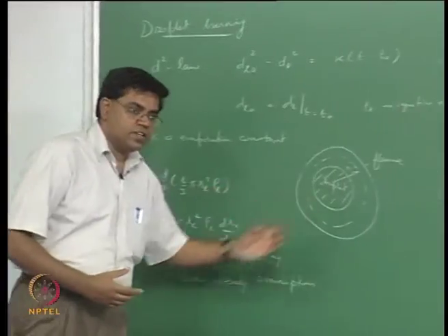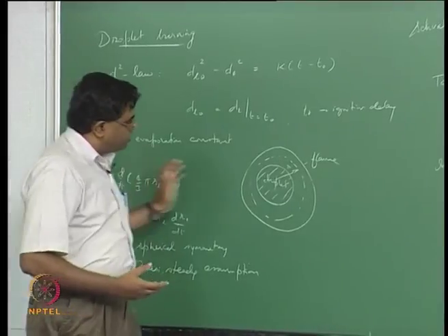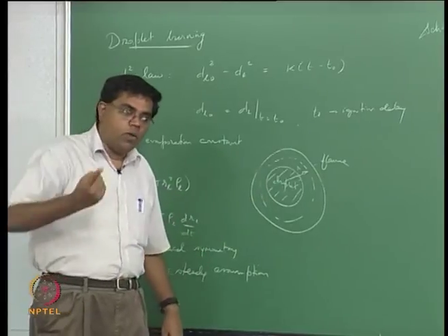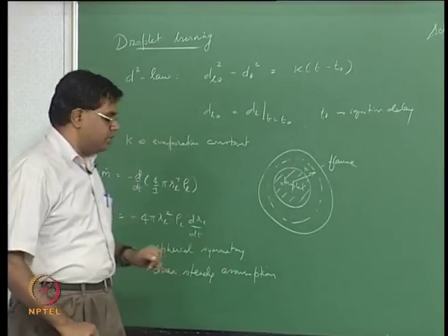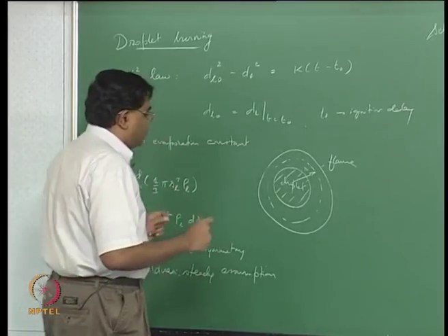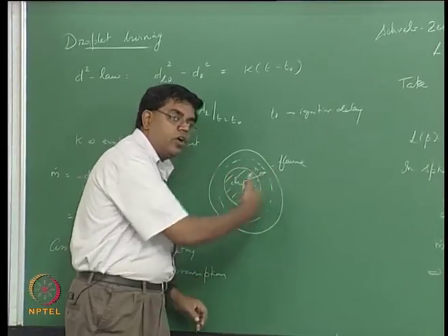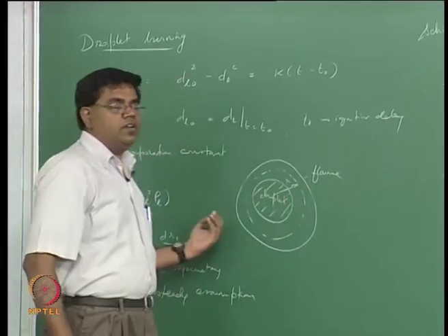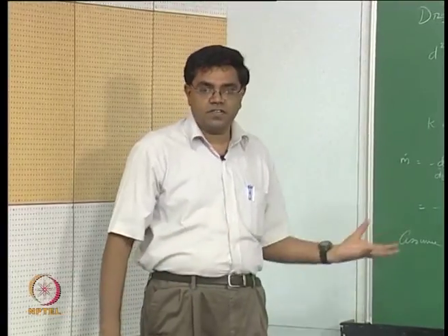In the other case you get this, and of course when you have an oxide lobe and you begin to think about a flow field, it becomes unstable and can start wobbling and so on. So in reality this is a lot more complicated problem. The point I am trying to make is that there are these problems where we would expect the oxide either to collect to one side or to penetrate the surface in liquid form and mix, whereas that is not necessarily the case with oxygen.